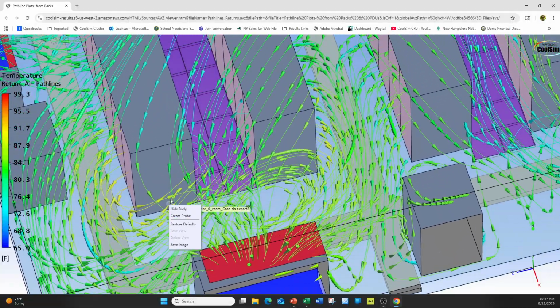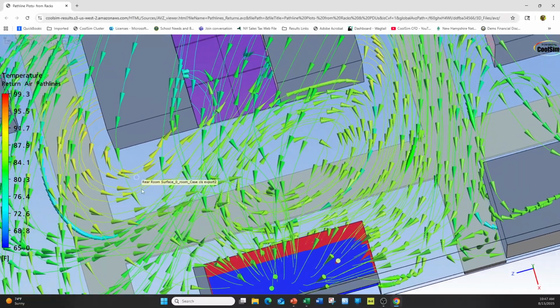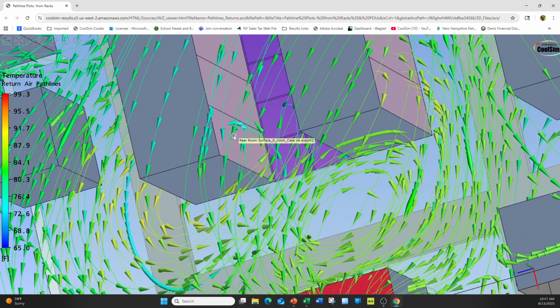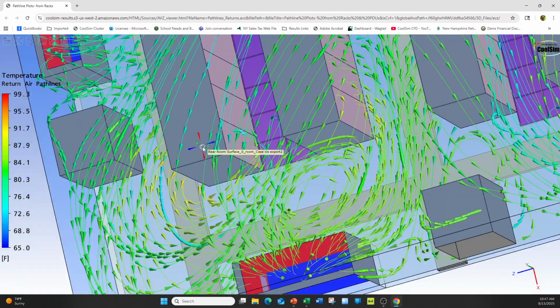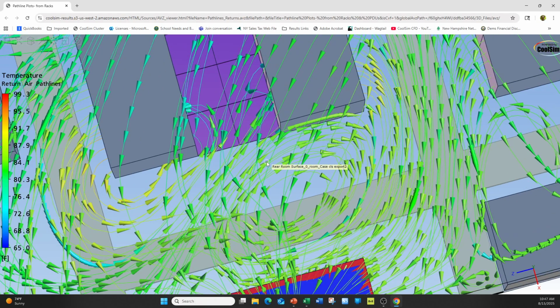So let's take a look closely at this image. You can see, as I turn this to the top, that this rack is wrapping right around. The air is coming around the back of it and back in towards the inlet. This is called rack recirculation, and this occurs when the performance of this tile is not sufficient. The server must get its air from somewhere, so it effectively breathes its own exhaust. It intakes the exhaust coming out of the back of the rack around to the intake.